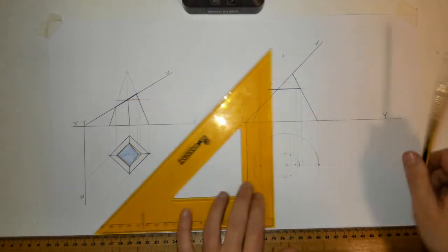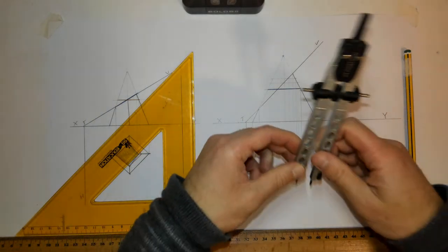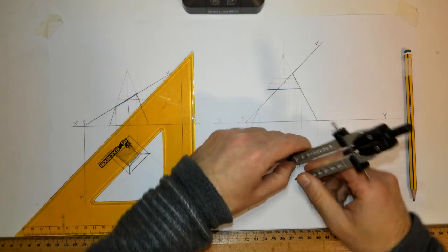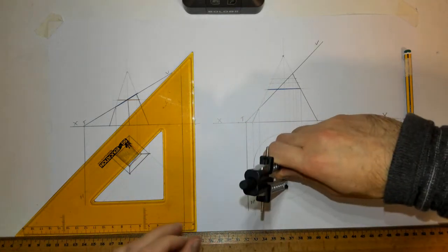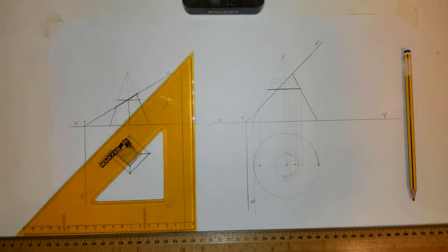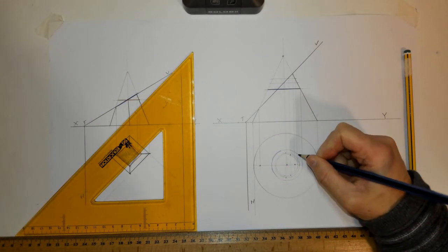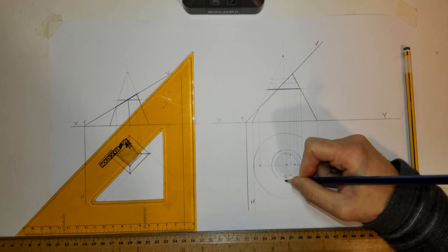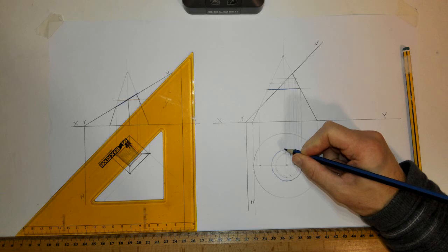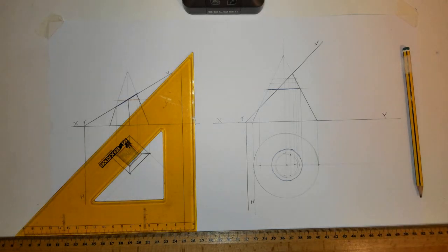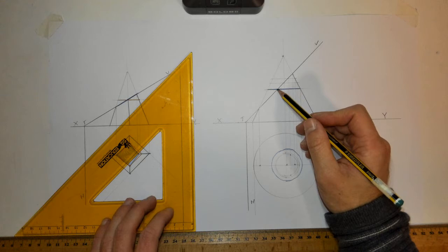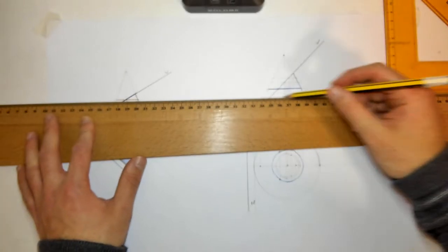So I take the extreme point out, draw my circle there, and then use my blue to go around it, to show that that horizontal cut that's blue appears as a circle in plan, and the exact point where that circle cuts is there. Take that down to hit my blue circle below at those 2 points, and then I can take maybe 1 or 2 more cuts.